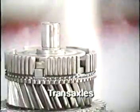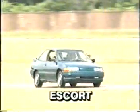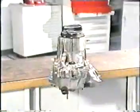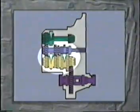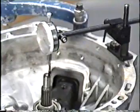Inspection and repair procedures for transaxles are very similar to those for transmissions. However, there are some differences. The front-wheel drive transaxle combines a transmission and a differential in a single housing. After disassembly, you'll notice that a significant difference in the transaxle is that it doesn't employ a countershaft. Instead, gears on the input shaft mesh with gears located on an opposing main shaft.